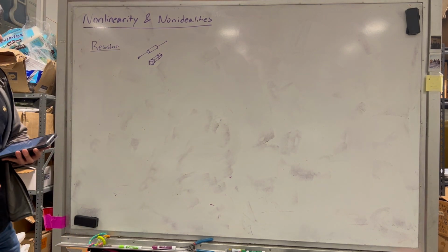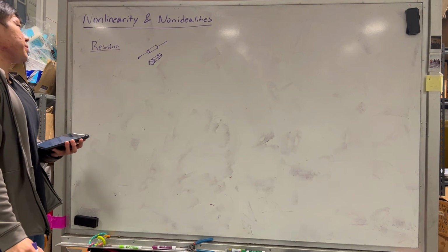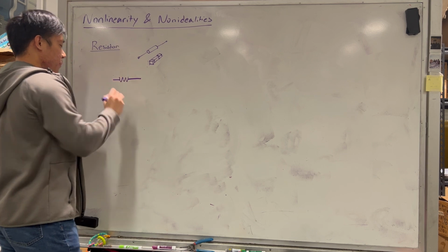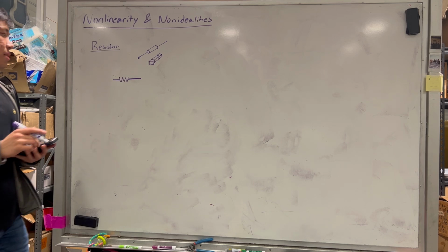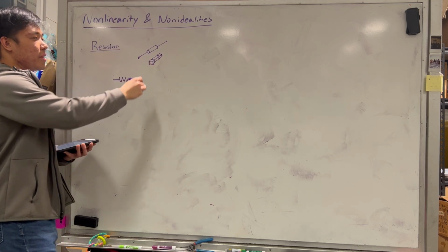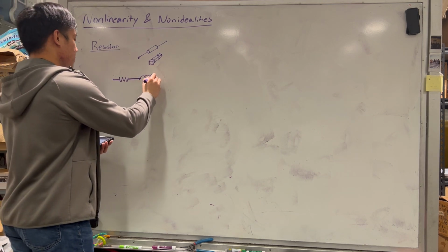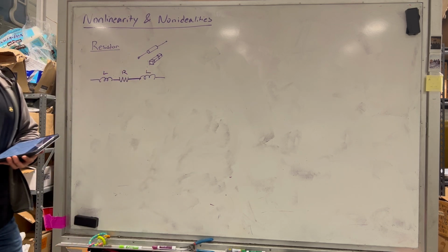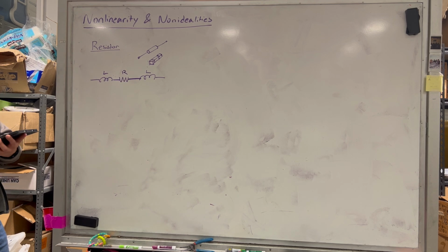And well, what is a wire? At the end of the day, a wire has some inductance. So when we model a resistor, everyone's familiar with just the regular resistor model. And then now we add the inductance of the leads. Since wires have inductance, these contact points on the SMD components can also be thought of as a short wire, so they have some amount of inductance. Two inductances here to represent the two different types of connections that can be made.